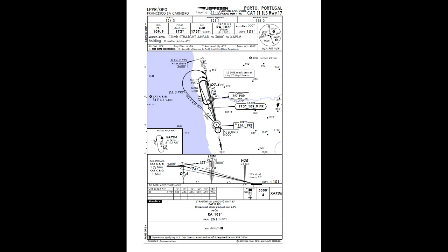Again, minimum safe altitude is again 2,600 feet. We will join directly and shoot directly from DME 12 from Papa Roma Tango at above 2,600. Then we will join the ILS at DME 7.6 on the ILS, and then we will join the glide path that is 2.7 degrees, not the standard 3 degree glide path. It is 2.7 degrees on heading 173, and we descend until the minimums that are actually 100 feet decision altitude or radio altimeter 108 for all the categories.